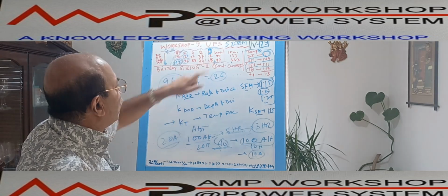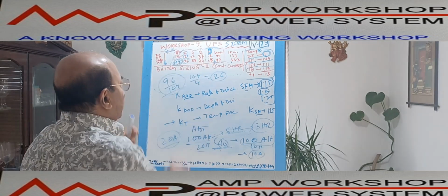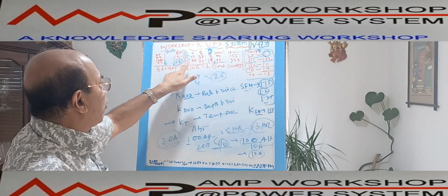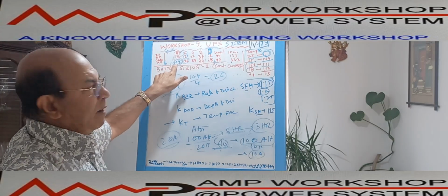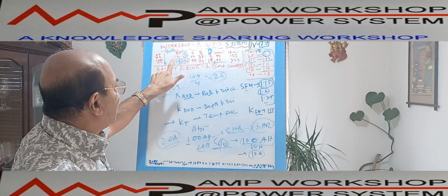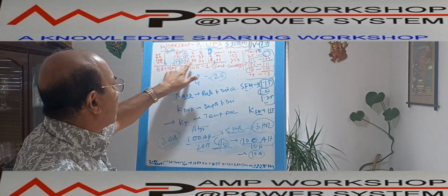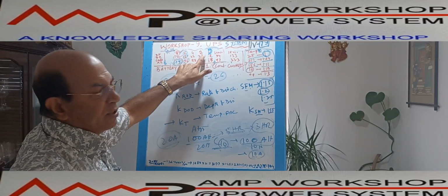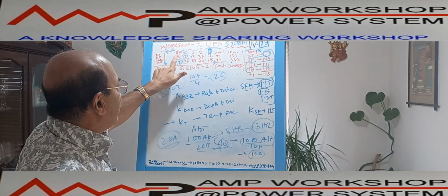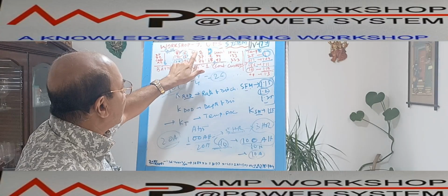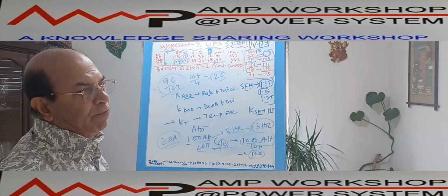You see, if I go for 1 hour or 2 hour discharge, how much is it giving? It is giving only 74 ampere hour, whereas my battery is 104 ampere hour. So I am getting only about 60% of this. I get 60% of the rated ampere hour when I discharge the battery at about 3 times the rate. 13 ampere is the rated condition, and I am overloading the battery 3 times. At that moment I am getting only 74 ampere hour.